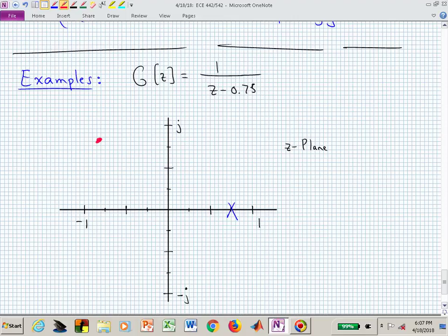We know that the closed loop system has what structure if it's proportional control? This you probably should have memorized, right? It's CG over 1 plus CG, and C, our controller, is just a K. So this is now KG over 1 plus KG.